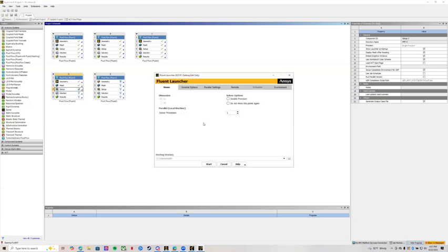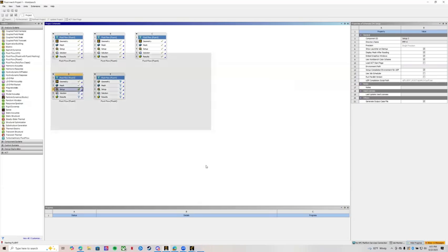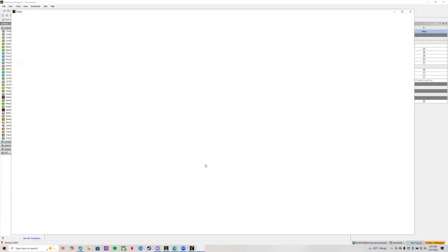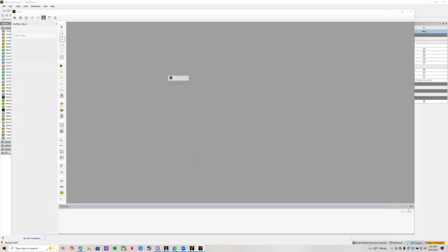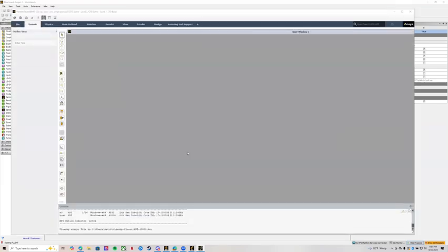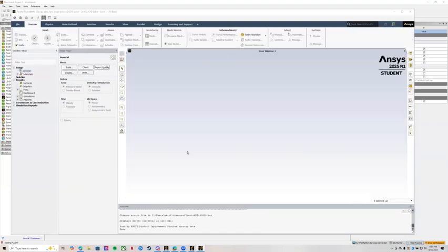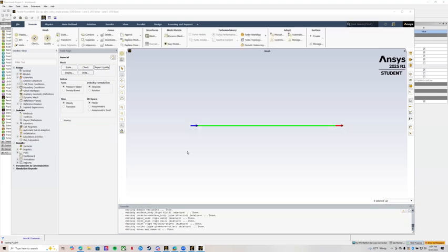This is where you're going to make your conditions for the flow. So biggest thing here is we get the meshing and geometry done. That's more or less just building our pipe. Now the setup is where we actually can start putting the conditions in to create that Poiseuille flow. So this first one's going to be our Poiseuille flow based off of the dimensions and everything. Now in this part, you do need to take into consideration what you want your numbers to be. The recommended thing to do is make your density just 1, and then your viscosity and velocity. You can just calculate those along with what you want for the Reynolds number to be.